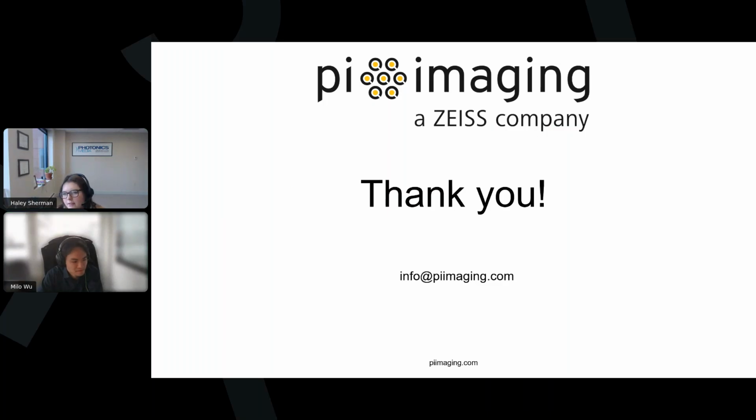Okay, last question I have is, is cooling using thermoelectric technology used to improve resolution? So cooling helps with controlling the noise. If you cool the camera, you have lower dark counts. In our sensors, there's a Peltier cooler in the box, maintaining the sensor at room temperature so it does not heat up over room temperature. This is to help with the noise. It doesn't help with the resolution.